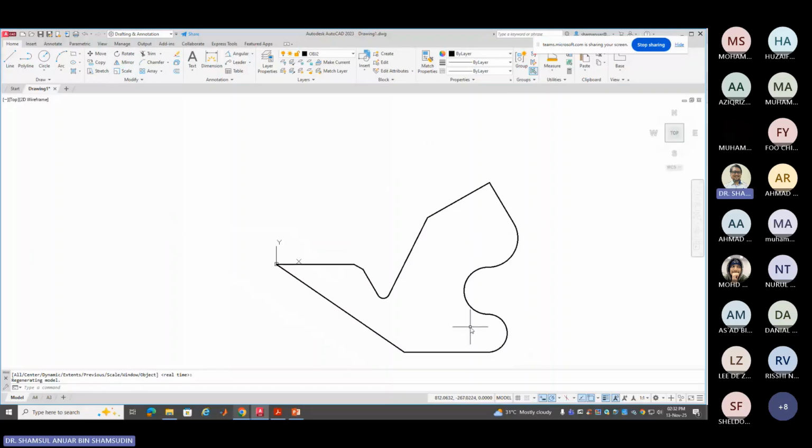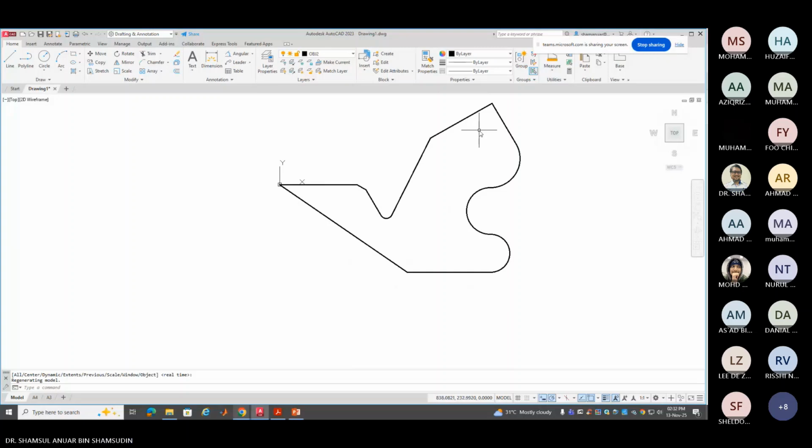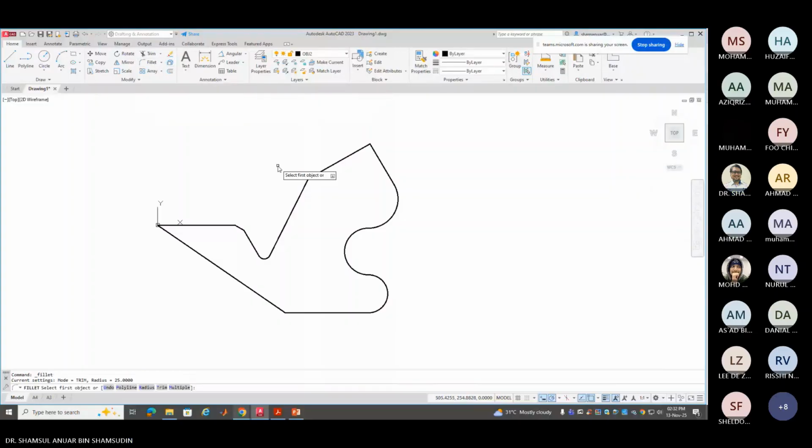Okay, and maybe over there we can also make it less sharp. So back to fillet. Maybe you can change the radius again, make it 50. Now trim that, trim here. Okay, ain't that beautiful? So once you have got to this point, we can also add another complexity.